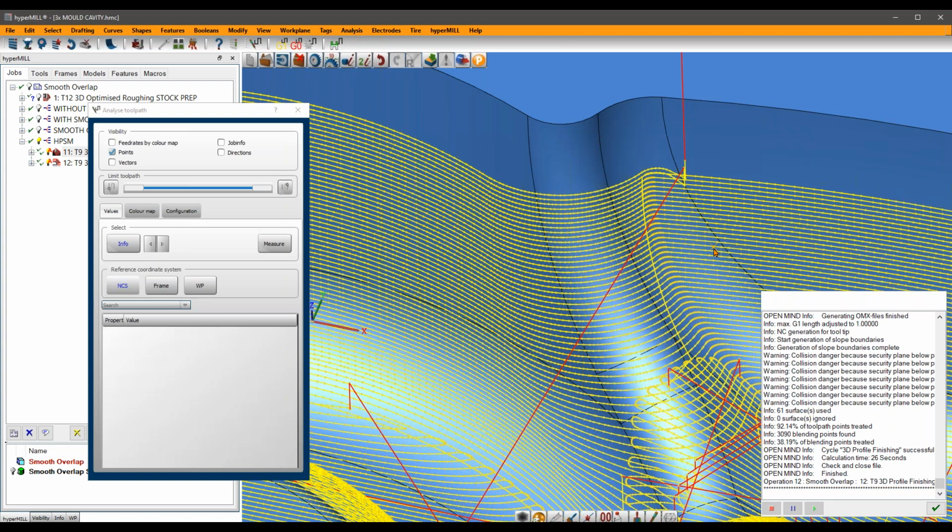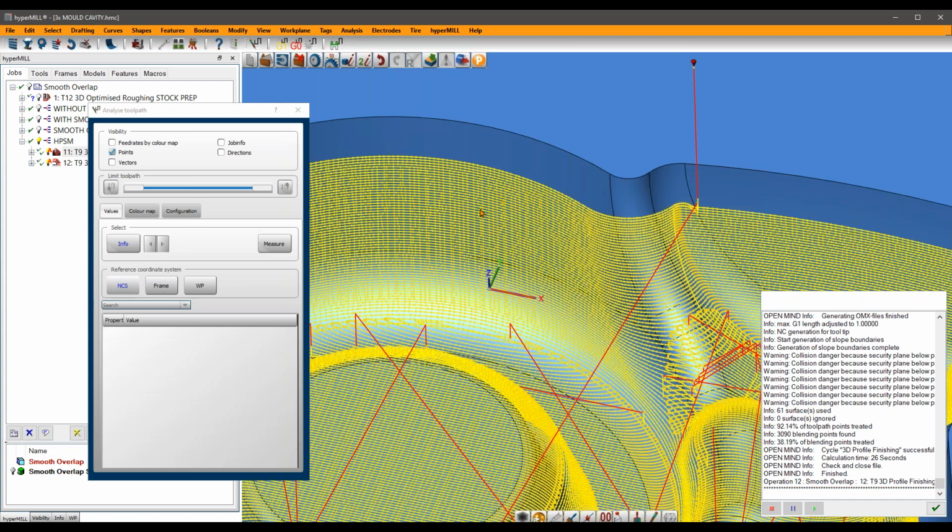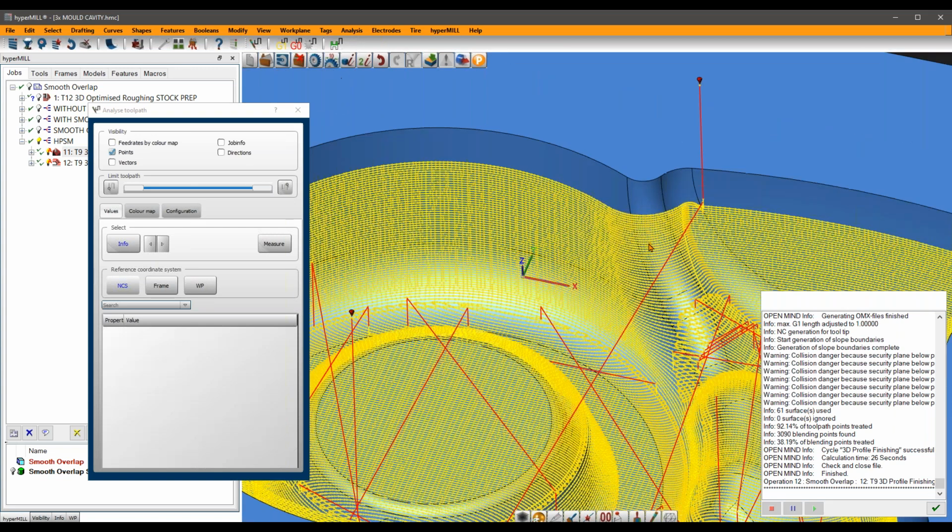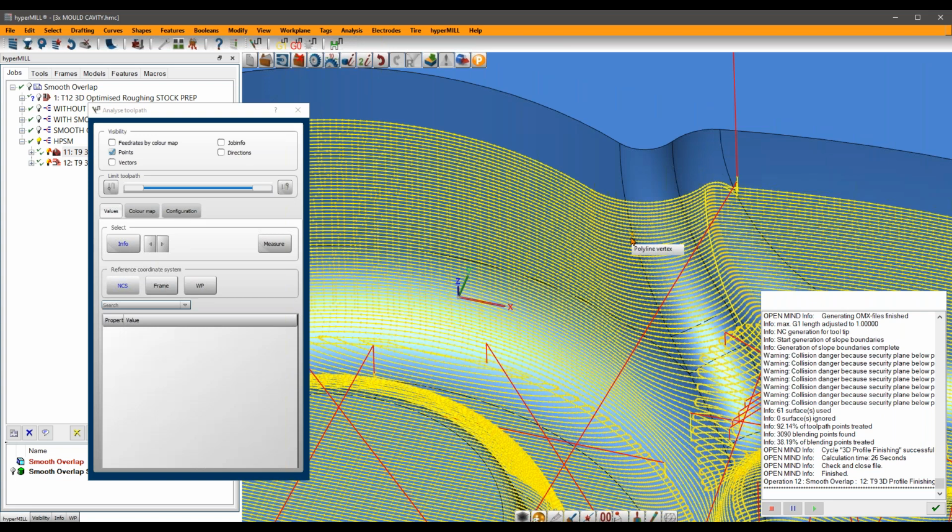Okay, and they are adjusting and splining the toolpath within that. So you can go down to a micron, even sub-micron machining. But realistically, okay, don't go going sub-micron if you've got a 30-year-old machine. Okay, it's not going to work as well as you think it will.